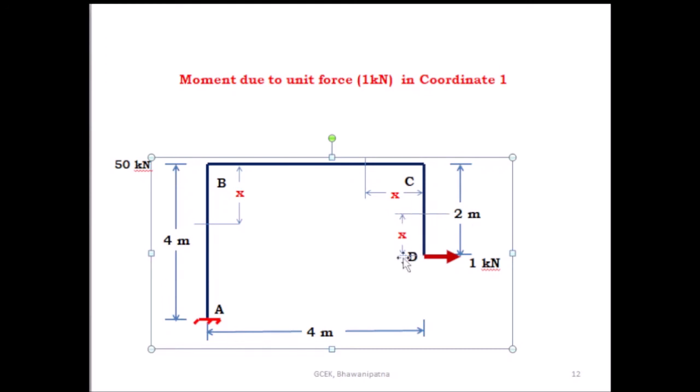What is the moment here? Take a section at a distance x from point D. Then what is the moment due to this unit force? 1 into x. This is in the anti-clockwise direction, so take this as minus x. This is minus x in span CD.